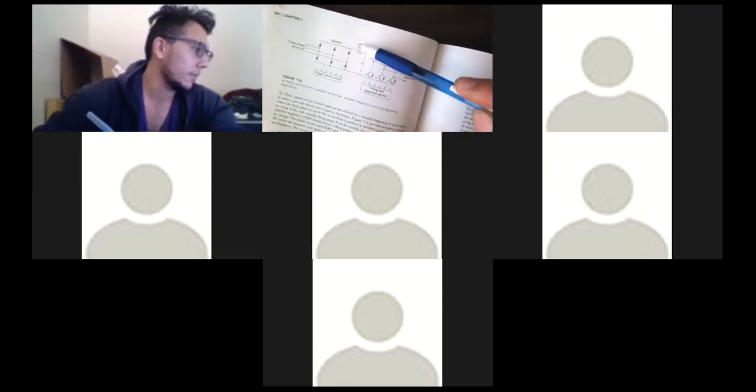So we don't even have to have three-phase AC power on the left. All we need is single-phase AC power, because all we need is DC right here. So single-phase to DC, DC to three-phase AC. That is the high-speed electric train.